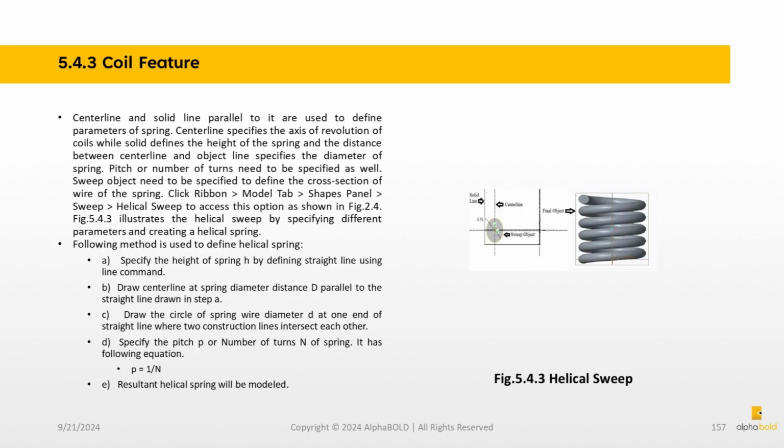Thread Feature. This command is used to create a thread/tap feature on a cylindrical face. A thread is added to the outer cylindrical face, whereas a tap is added to the inner cylindrical face of holes. For this purpose, the helical sweep command is used in PTC Creo. A helical sweep object is created on the relevant cylindrical face. The thread profile is adopted by the sweep object while the remaining parameters are the same as in helical sweep.